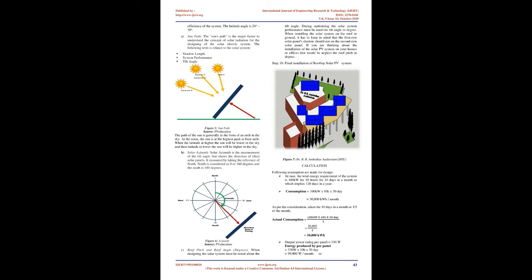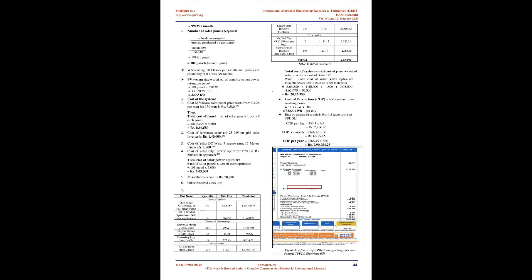We are considering a double structured module as per market trend. We are making multiple modules in a horizontal row using the copy tool and keeping the distance between one module and another at 24 mm, which is known as a solar array. We are arranging the solar array sets on the top of the whole roof while considering the pitch, which is the distance between the starting point of the first solar array and the starting point of the next solar array.